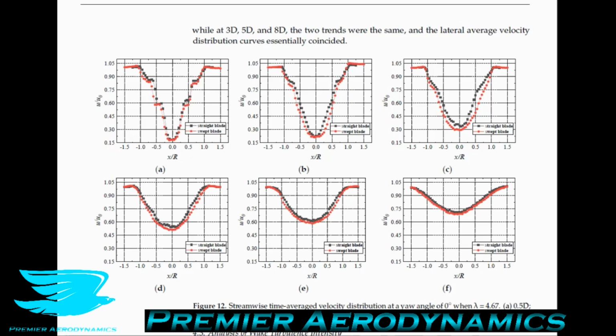Moreover, because of the tip acceleration effect, the velocities at the blade tip were higher. The velocity deficit in the central vortex region was prominent, and the minimum streamwise velocities only recovered to about 18.5% and 21.7% of the oncoming flow. As the position moved towards the blade tip, the wake progressively recovered. Additionally, it can be clearly seen from the figures that the wake recovery of the wind turbine with swept blades was slower than the one with straight blades.